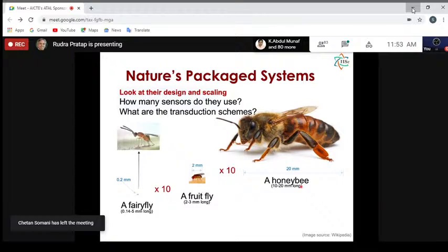Capacitive pressure sensors basically work like that. How much has it deflected? And that depends on how much pressure or how much force is being applied on it. Now, depending on what kind of material it is, its deformation is related to the force which acts on it. And that's the correlation that tells you what the pressure is on the other side which is deflecting it by so much. How much it is deflecting by, that we get from our capacitive sensing, right?